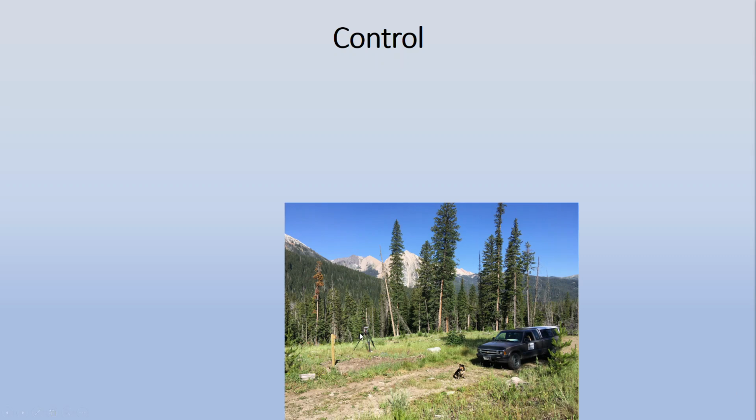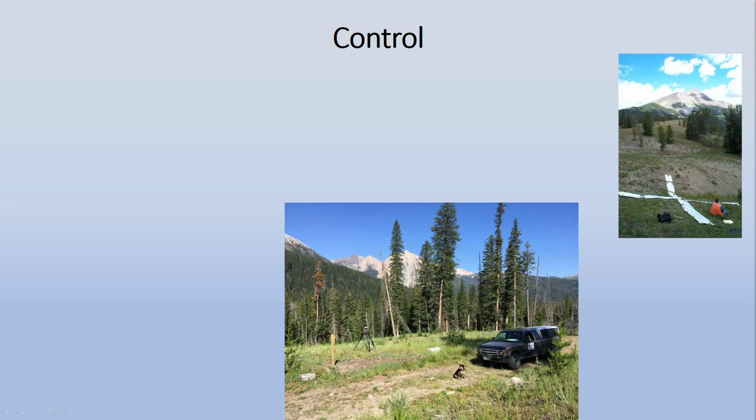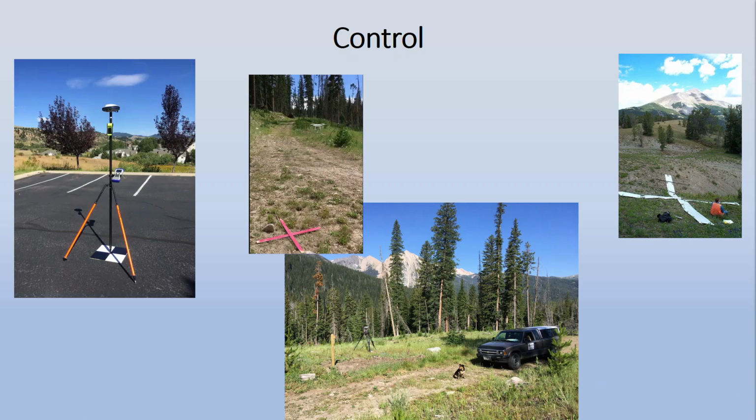And I've got some examples here of an RTK GPS control base. It can mean a big target panel point for aerial photography, back when it used to be done primarily by airplanes, as recent as 5-10 years ago. Anymore, people are performing their own photogrammetry with the advent of drones. And you can see here's my little drone in the photograph, and sometimes all you need to do is put a cross of lath painted up pink, and these show up actually from a 400-foot altitude.